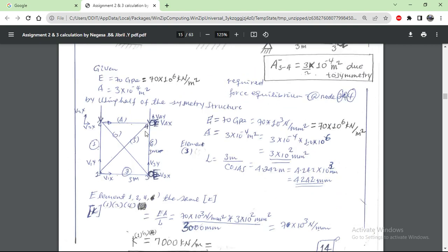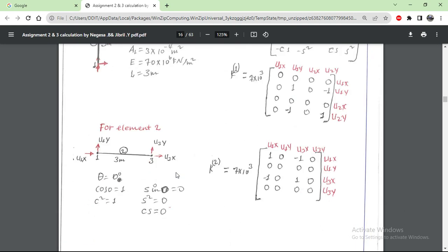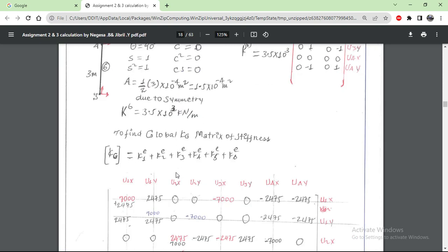So in the x direction at points 3 and 4 it is fixed. The rollers move in the y direction only. At this one u4x is 0, and u3x is also 0. It is stationary. Due to these reasons, we take 0 as the boundary condition.